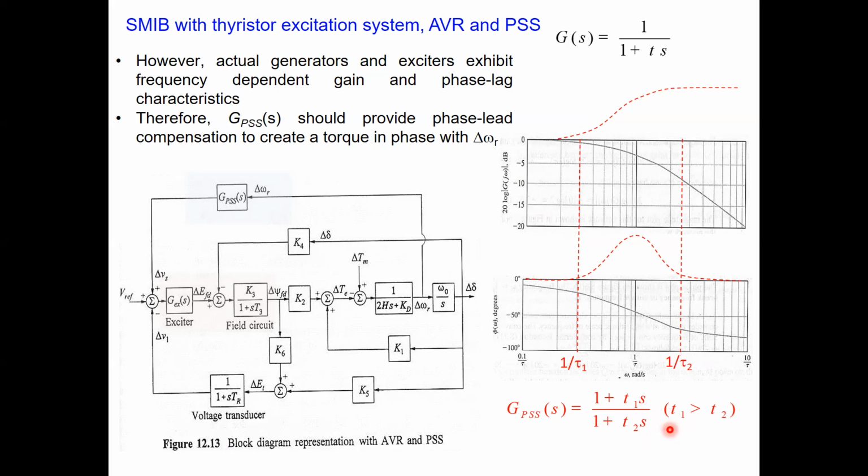But again, we cannot have full compensation. As you can see here, this is T1. If we say T1 is the position of the poles here, this is the pole, sorry, this will correspond to the position of the zero, and this will correspond to the position of a pole. What you find here is the magnitude, if I say this one, it will be like a lead compensation provided here. So as such, we have both lead and lag compensation, because we cannot have full compensation here. Thus it represents the range of frequency of interest here, and thus provides the phase compensation.